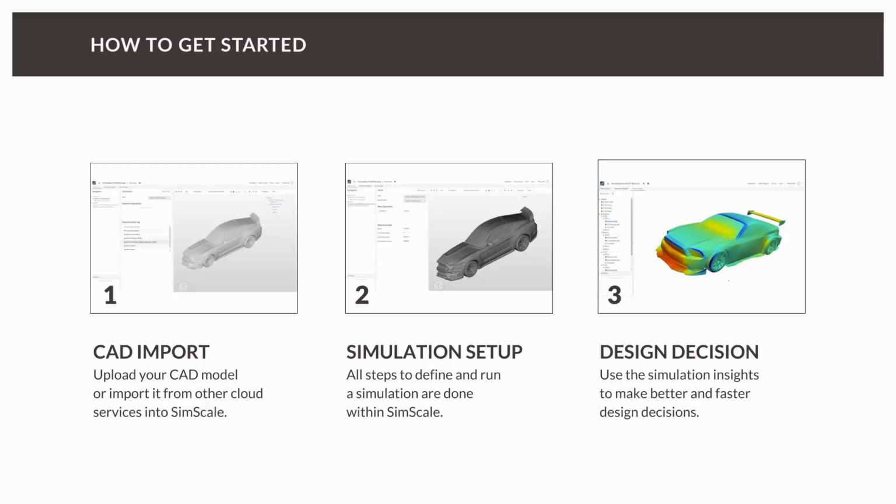So the aim of the meshing is to adapt or to create the mesh. And there you should follow the concept of as many as necessary, as few as possible. So the perfect mesh will resolve all gradients where necessary and will be very coarse wherever possible. And once you've created the mesh, and this can be a very computing intensive part, you're going to set up a simulation, explain like where's the inlet of a wind tunnel, where's the outlet, and then you can run the simulation and visualize the results in your web browser or download them for further post-processing.